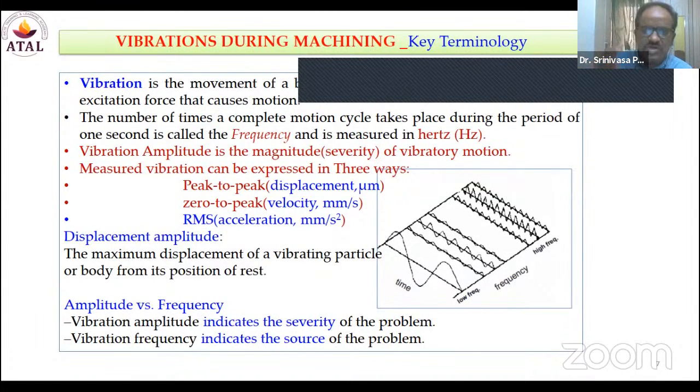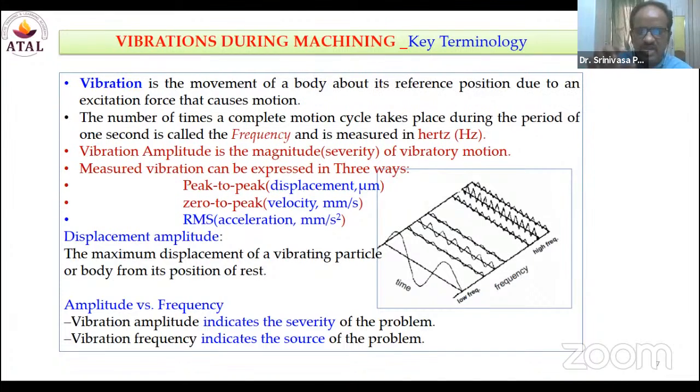Initially, you will capture the amount of vibration on the time scale. For a time period, you can adopt any sensor. It is going to collect the information, the data. That is called data acquisition through a sensor. Quantifying the signal can be done with signal transformation functions. I have used 2 different signal transformation functions in this presentation, and I'm going to show the clear difference between them.